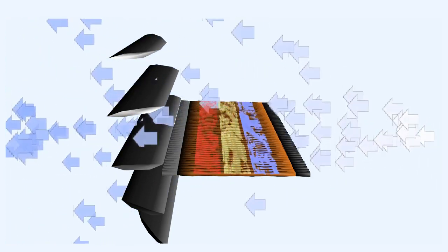To the rear of the cooler, some oil would still flow, but being insulated from the cooling air by more and more stationary cold oil, it would get hotter and hotter. The instinctive reaction of the inexperienced operator to the indications would be to open the oil cooler shutters fully. But this would just cause the oil temperature to rise faster by thickening the insulating layer of cold oil in the front of the oil cooler.